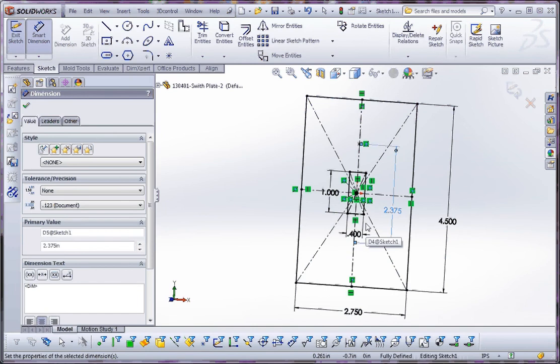So now you'll notice, and this is kind of a phenomenon that you'll see in AutoCAD too, that now we have, it's kind of like a donut in a way. When SolidWorks or AutoCAD, with hatching or with the solid feature we're doing here in SolidWorks, usually starts in the middle of the object and will populate that with substance. And when it finds a sketch line, on one side it's going to provide substance, and on the other side it's going to provide a void. So when it gets over here, it's going to be a void on the outside from there on out.